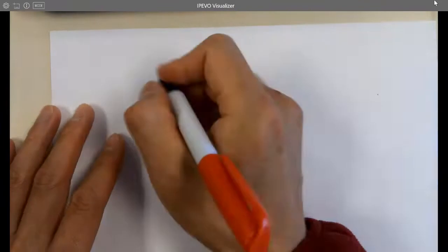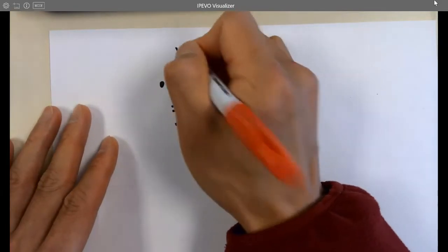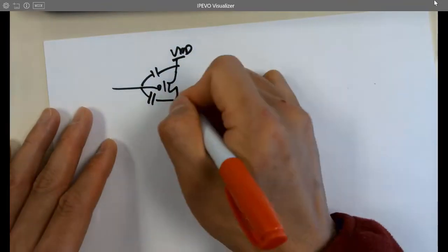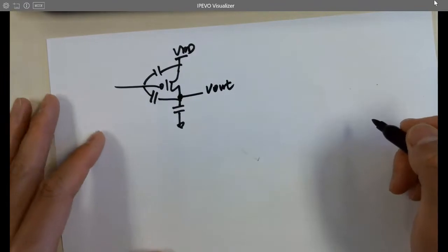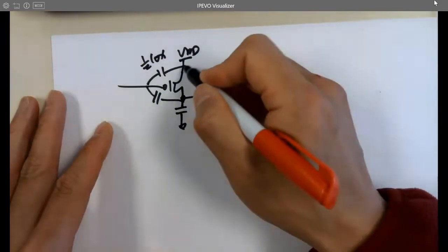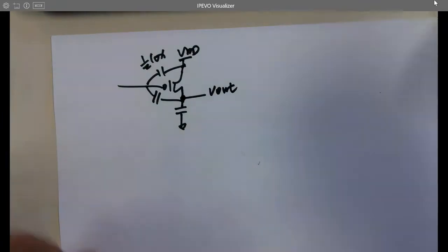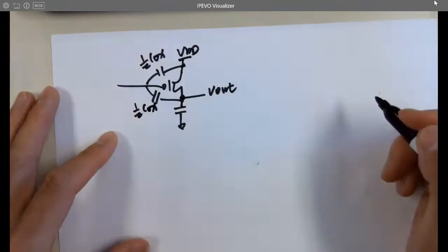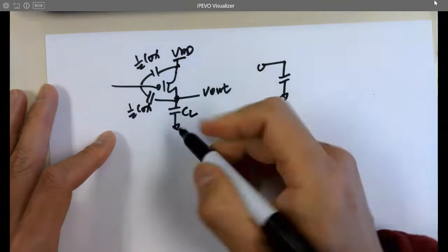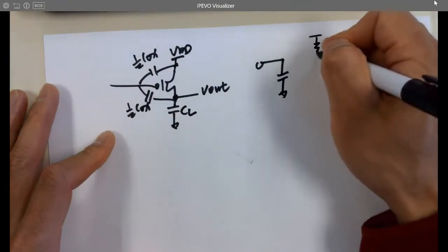So now let's look at the PMOS. How do we model a PMOS? VDD. VL is here, it's green. So this is half of Cox, right? If one terminal is tied to VDD, it's not changing on both sides, so this one doesn't have that mirror effect. But this one has. This is C load. I forgot how the textbook drew that equivalent circuit, but it didn't make too much sense to me, so I redrew it in a slightly different way, which makes more sense.